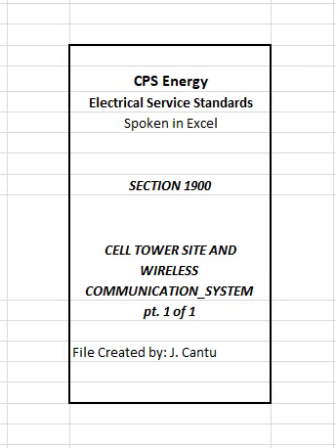CPS Energy distribution pole may be located either on curb side of sidewalk or non-curb side of sidewalk, refer to figures 1903 and 1904. B. Overhead service on customer meter pole. Service and metering equipment shall be designed to be installed on customer's meter pole along with necessary communications equipment.